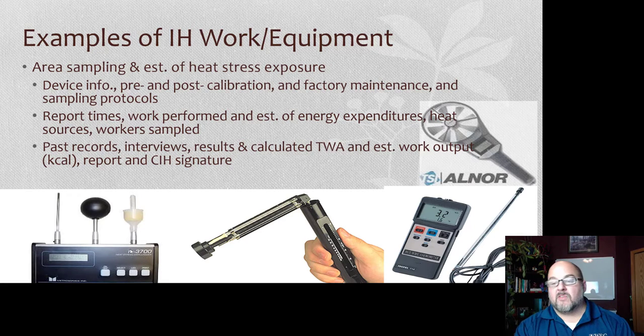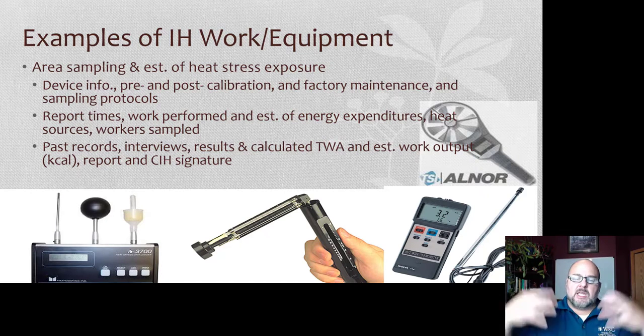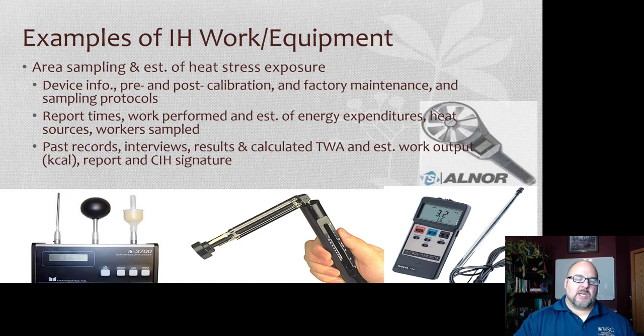On the right, we've got some velometers. One is a propeller, one is a hot wire anemometer. It's a combination of all these things that you use to determine the heat impact on the person. Then you have to take into account the heat being generated by the work they're doing. You can use tables from ACGIH to determine whether there needs to be a work-rest schedule, or if workers need breaks for water or a Gatorade with an electrolyte. Not supporting any one particular brand. There's like Squench and stuff like that.